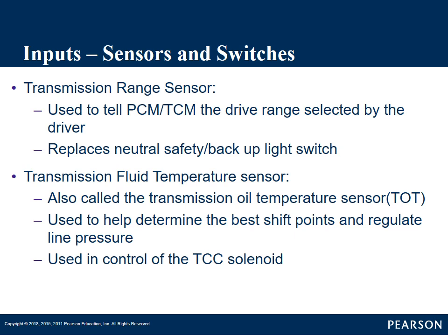So this is, I would say this is just as important to the transmission as the coolant temperature sensor is to the engine. Okay, this would be a higher priority to the transmission controller than the engine coolant temperature would be. If you remember, one of our inputs that we use from the engine for the transmission is the engine coolant temperature sensor, but the transmission fluid temperature sensor is more important to the transmission.